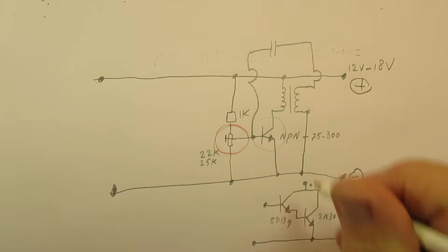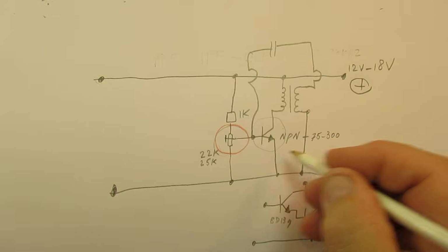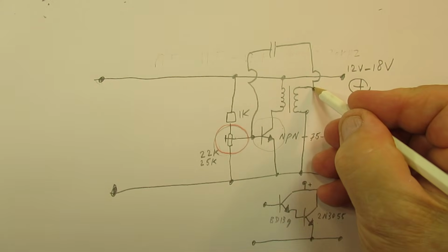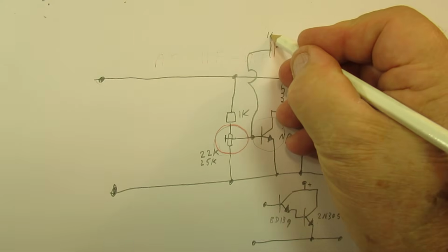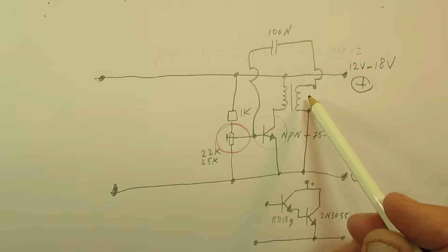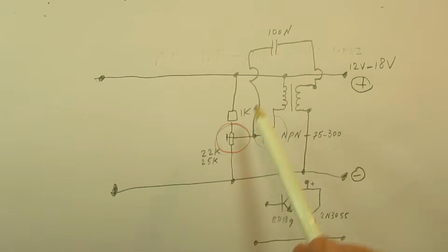So this part here, the Darlington, instead of that 1 NPN transistor. And the most important thing is this, say, use here 100 nanofarad. That often works. The transformer itself, the value of the capacitor, and the bias set the frequency where this works.